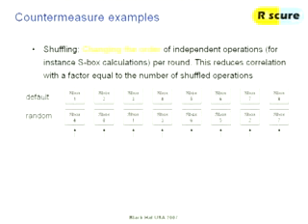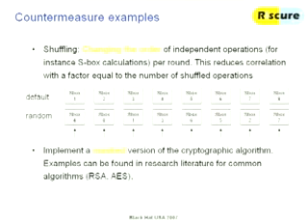It goes something like, if you've got 8 S-boxes, to get the same correlation, you need 8 times 8 more traces. So 64 times more traces. It goes by the square. So that's significant. If you take 100,000 traces and you have to take 6.4 million, that's a significant difference.